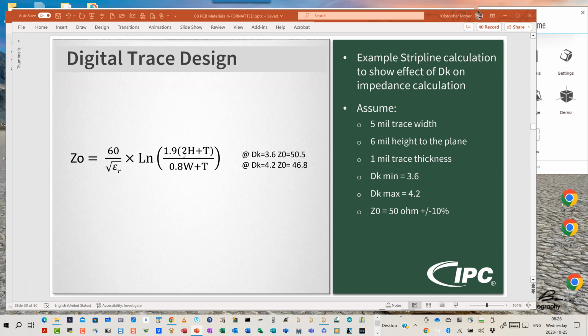And so, yes, you could go thicker to try and play with those numbers so you might get the controlled impedance. However, if you make your dielectric thickness too thick, now your loop areas are so large that you get so much inductive coupling that instead of being able to route a bus at like 5 or 6 or 7 mils gap between the copper features, I need 15 or 20 mils gap between the copper traces. Otherwise, I get excessive crosstalk. And we'll see that when we get to signal integrity. Great, thanks. But absolutely great questions, everybody.